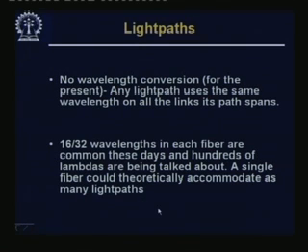So, no wavelength conversion for the present, and any light path uses the same wavelength on all the links its path spans. 16 or 32 wavelengths in each fiber are common these days, and hundreds of lambdas are being talked about. A single fiber could theoretically accommodate as many light paths.